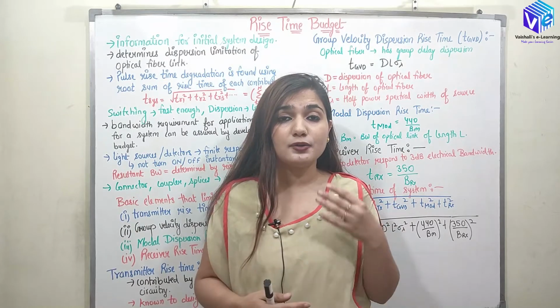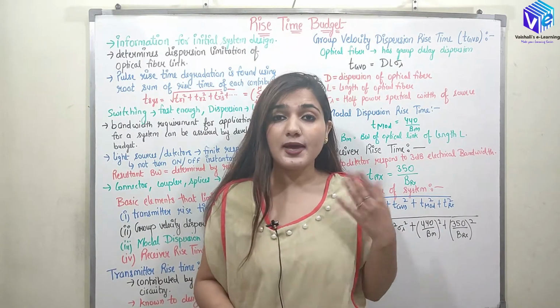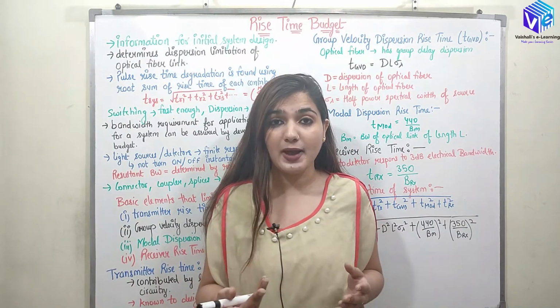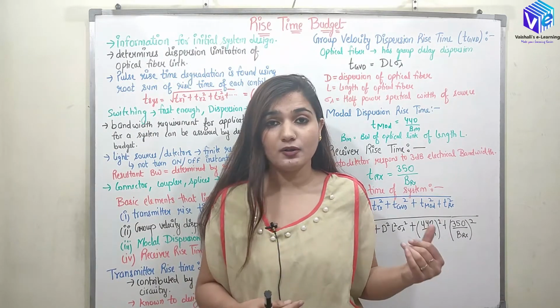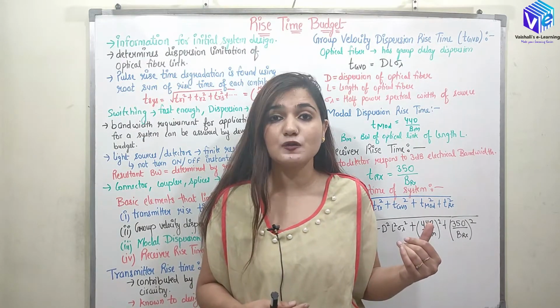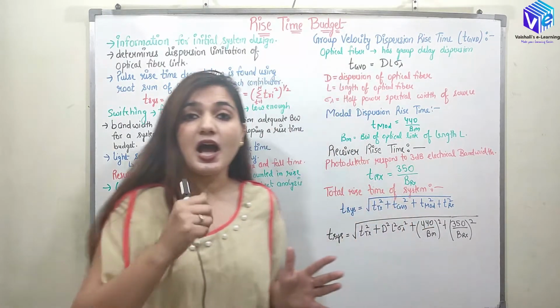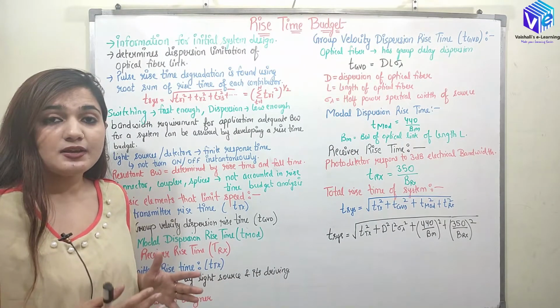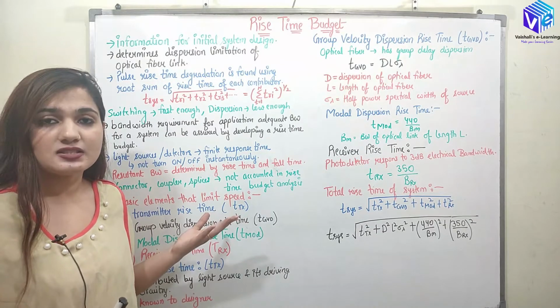Why do we require to analyze the time for a given circuit? We require to analyze the time for a given circuit so that we can have an idea about the bandwidth. And when we know the bandwidth, we can guess what is the speed over which the circuit is going to operate. So now for the system designing, I need to know what is the rise time analysis. With the help of the timing budget, I can design the system.